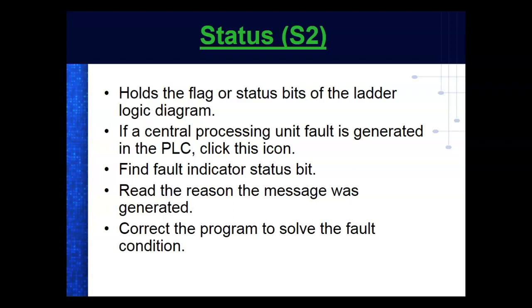By the way, if you get a fault, we got a PLC. Look at your PLC. The third LED from the right says what? Fault. If that ever flashes red, you've got something really screwed up in your program, right? You understand? And the status file will show us what that fault was.